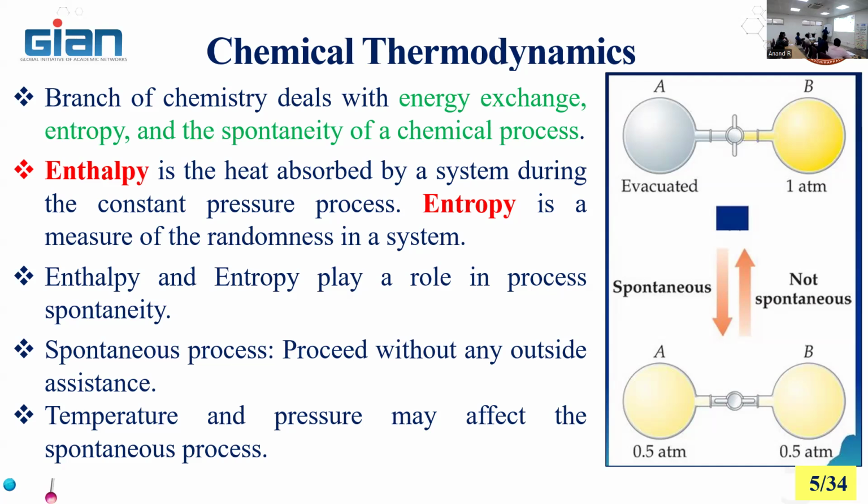If we substitute both, we can say R, the gas constant, is Cp minus Cv. So Q equals m Cp (T2 minus T1) minus m Cv (T2 minus T1) plus m Cv (T2 minus T1). So this cancels. Finally, you will get Q equals m Cp delta T, which is nothing but enthalpy.